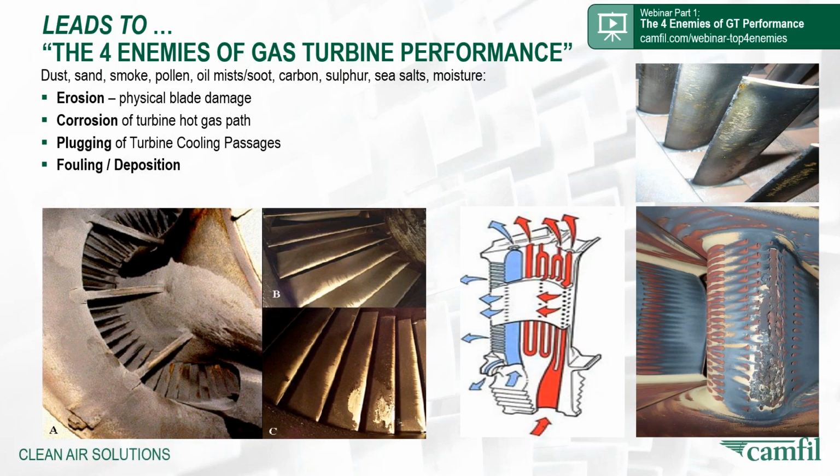Well, it's composed of either dust, sand, smoke, pollen, oil mists, soot, carbon, sulfur, sea salts, and/or moistures, all of which can lead to erosion or physical blade damage, which we can see over on the right-hand side top there, physically damaging those blades. Corrosion of the hot gas path. Some of those things will damage the gas turbine section. Plugging of the turbine cooling passage.